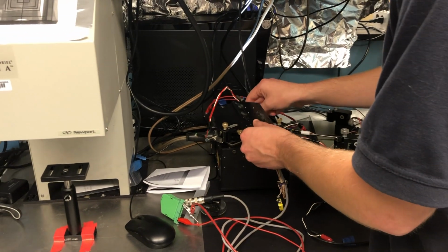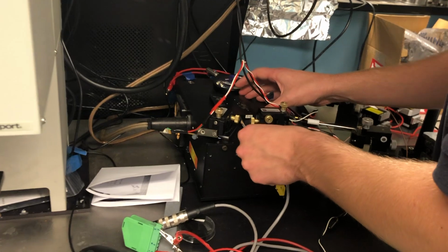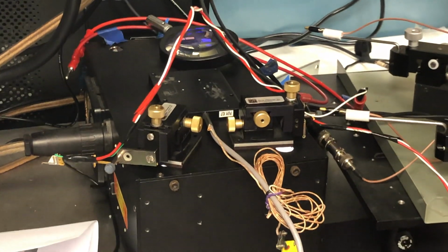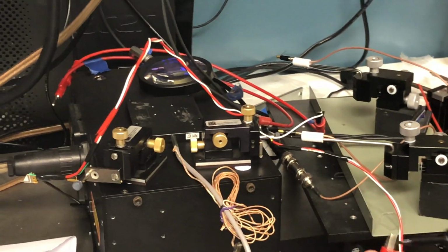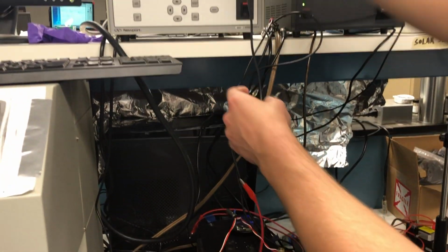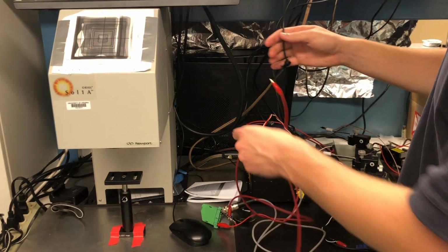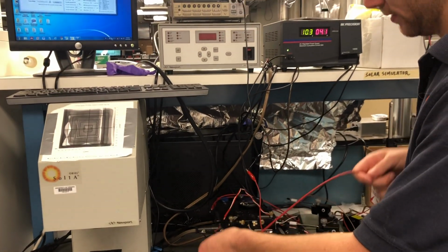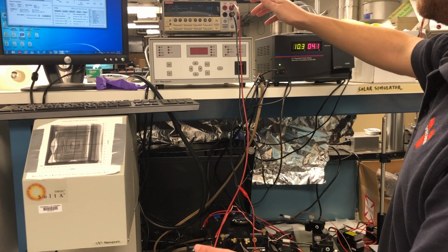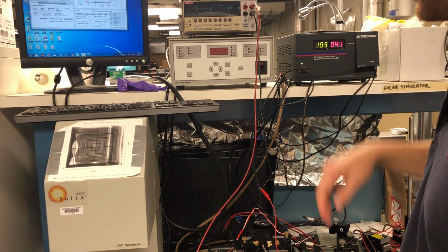So I'm going to line this up over the lamp here. We're just going to use the down-facing lamp just to make our lives a little easier, so we don't have to get probes. This thing has a nice little negative terminal, positive terminal, and we're just going to use alligator clips to connect to the negative and positive on the Keithley. So we're using the right side, that's the input output. If you have a 4-terminal method, you would just put it on the other two sides as well.